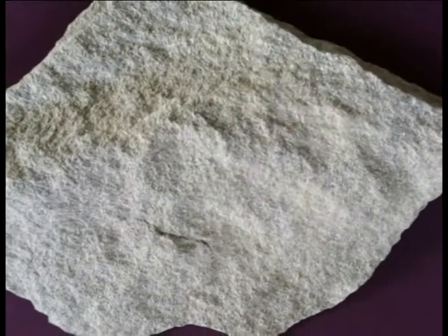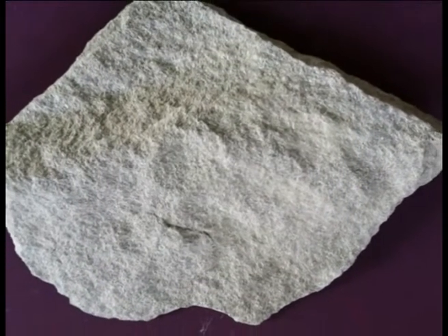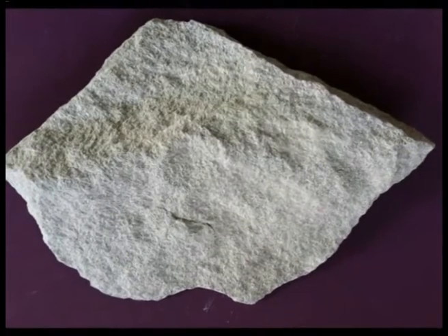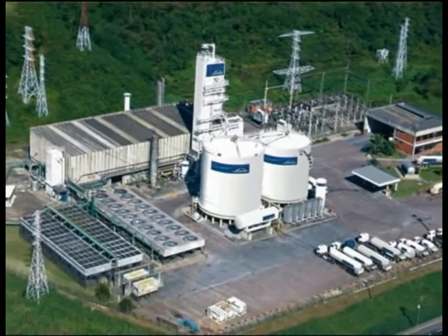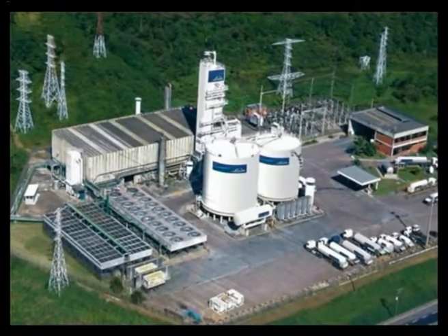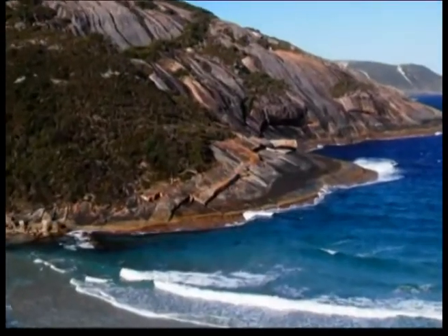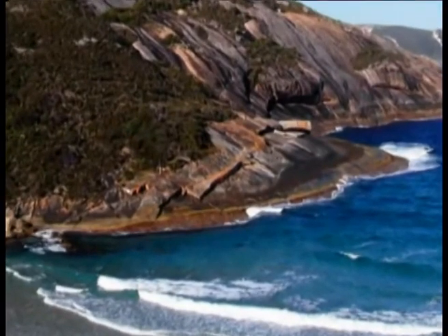The use of these limestones as facing stones, even if they are sufficiently hard, should be avoided in situations where the air is polluted with industrial gases. Second, where the air from the sea can approach them easily.